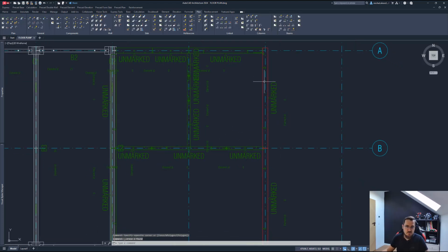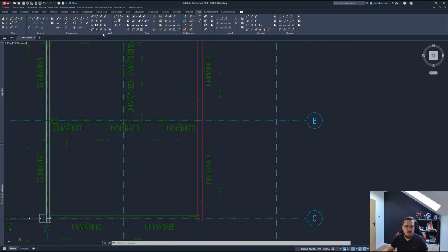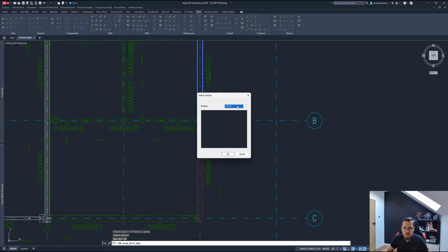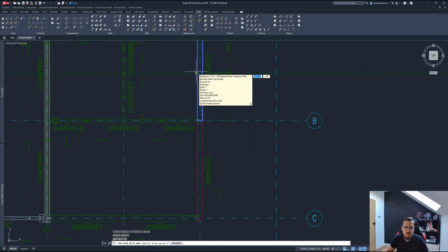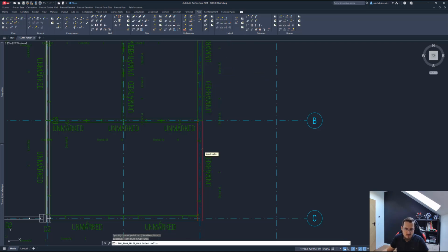No worries, we'll split those walls later, or just now, and you will see how easy it is to fix that situation. So this element is too big, fine. Let's split it, right? Let's use this particular end cap, around the middle, and accept that, and do the same here.